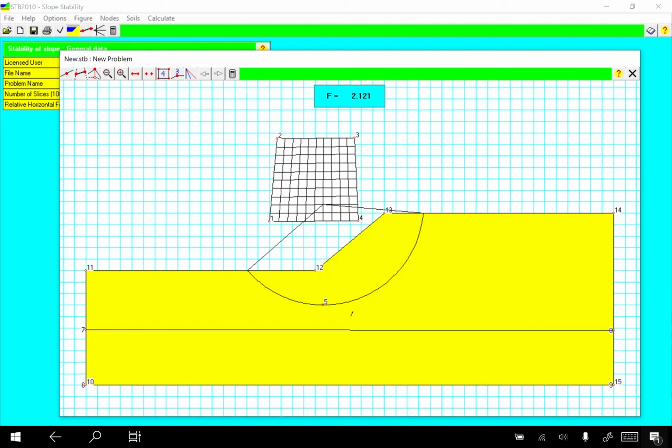The reason is that while the open surface water helps stabilize the slope due to the hydrostatic pressure on the slope surface, the groundwater hurts the safety of the slope because it creates buoyancy. So if we drop it to a depth that's far from the bottom of the slip surface, then all the soil is dry and strong. Because of that, the slope stability would increase again.